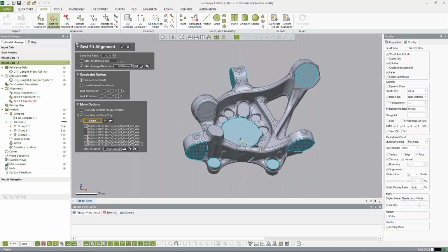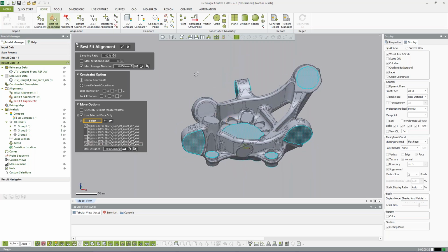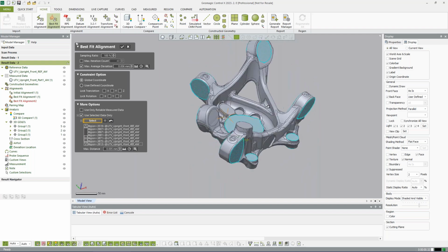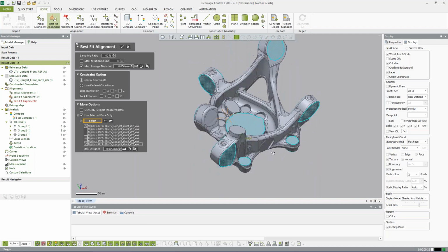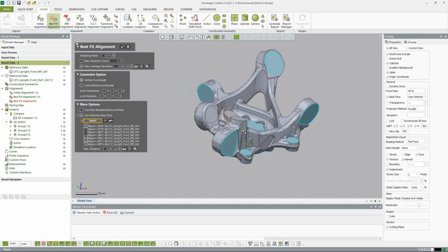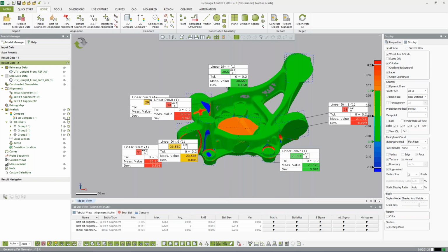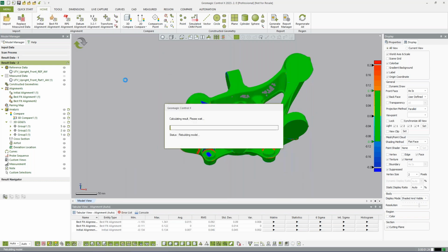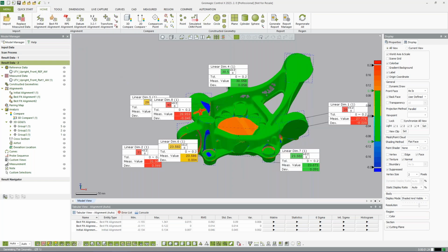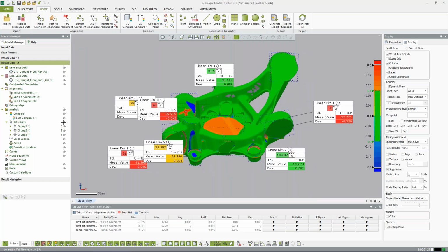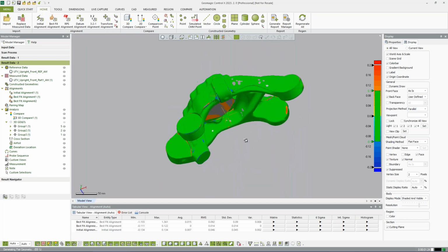So let's turn our compare back on, just so it'll rebuild. Let's grab all these things that we machined that matter for the part, and align to all of them, and see if maybe the casting is out, because maybe we shifted all those faces in the background and we didn't really know. So I'll come in now, turn these back off, and hit rebuild. And then we can recheck the color map here, but nothing really changed.